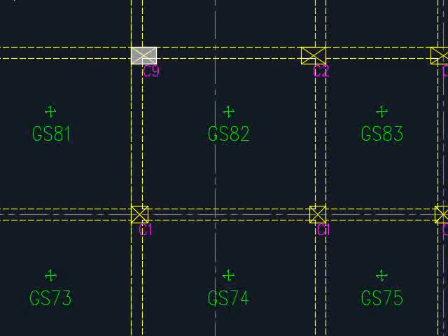For the common design, in terms of the size as well as the area of reinforcement bar, the capacity of the columns can be classified into several groups in order to limit the variety of column designs throughout the entire building. This is what you can do.